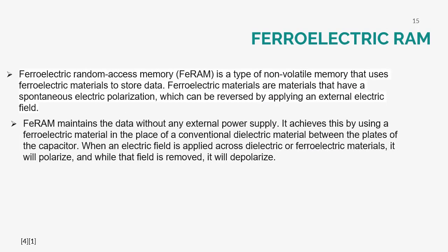Moving to the next non-volatile memory technology, that is ferroelectric RAM. Ferroelectric random access memory is a type of non-volatile memory that uses ferroelectric materials to store data. Ferroelectric materials have a spontaneous electric polarization, which can be reversed by applying an external electric field. FeRAM maintains data without any external power supply; it achieves this by using a ferroelectric material in place of conventional dielectric materials between the plates of the capacitor.